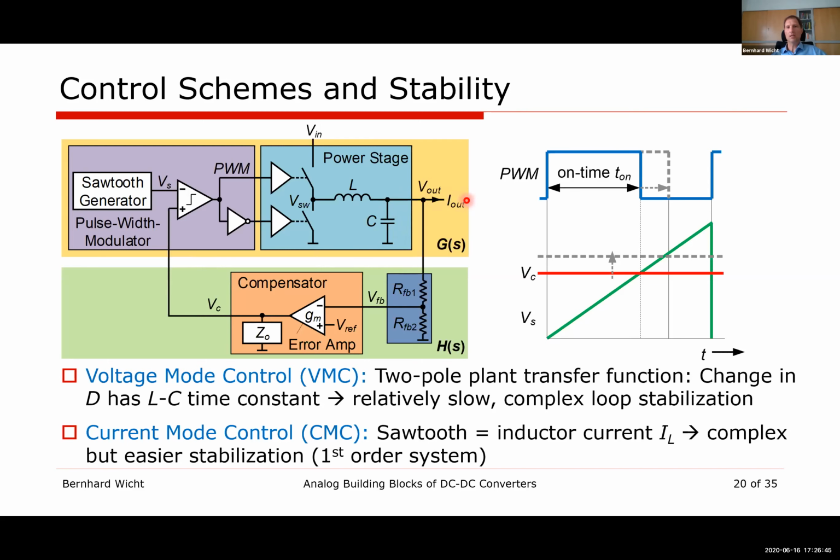It basically cancels all the ripple that comes from the remaining switch mode activity. And then the linear regulator gets a clean, noiseless output. That's the common practice. However, I know that there are some products that already are able to achieve very low ripple and very low noise without using linear regulators. But to be honest, I'm not so familiar with all these techniques.